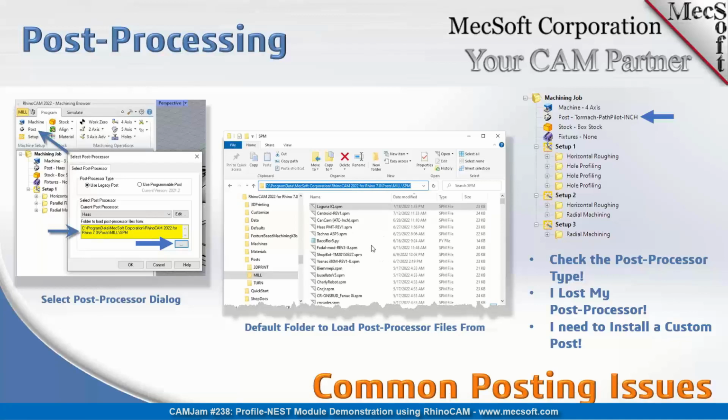Make sure your post definition file, if you want to keep it in this default location, is listed here. If you want to keep it in another location, such as on your desktop, or multiple users typically will have it on a shared drive in their internal network, you just want to make sure that this path over here, by picking the three little dot button there, is pointing to the common folder where you have your post processor files. And once you point it to the right folder, they will show up in this current post processor list.